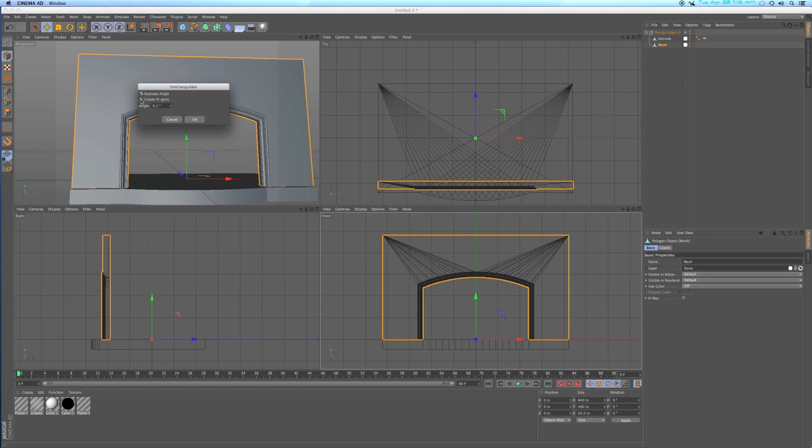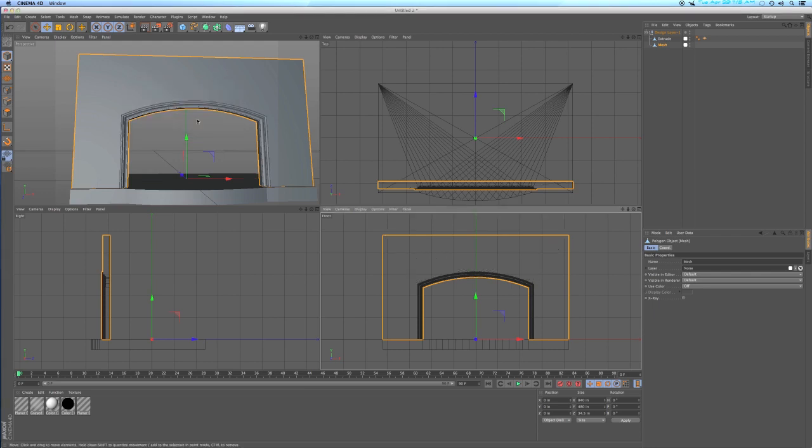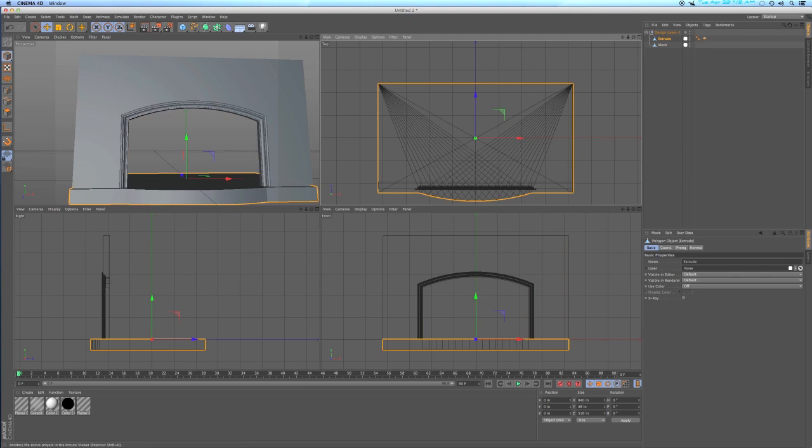I'm not going to explain what n-gons are, but it's a much simpler way of creating the 3D object. So create n-gons, say OK, and you can see now it's gotten rid of all those lines. I mean, it just looks prettier, and it's a much more efficient model. Now I'm going to select the stage floor, and I'm going to do the exact same thing. Untriangulate.